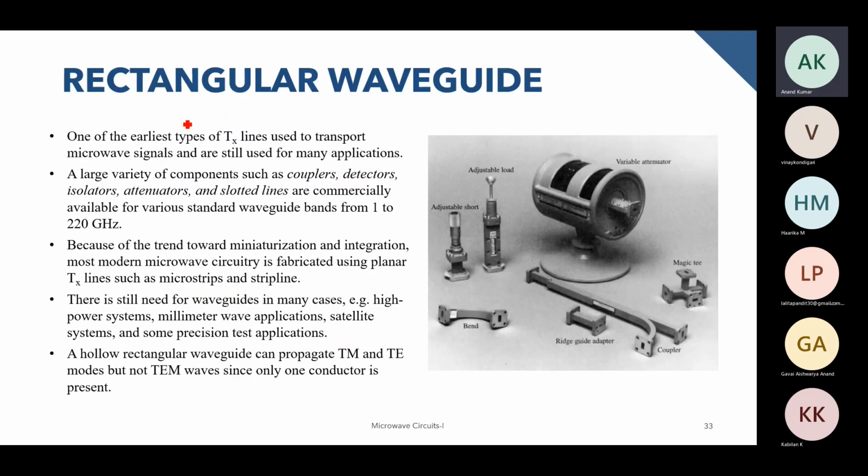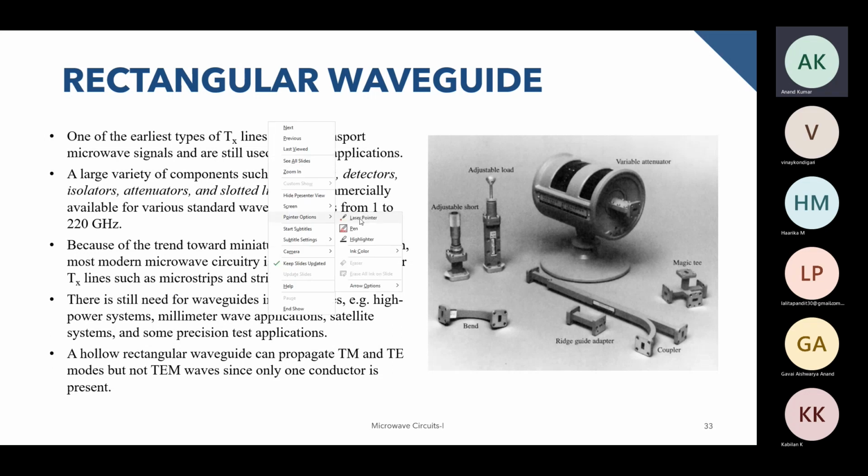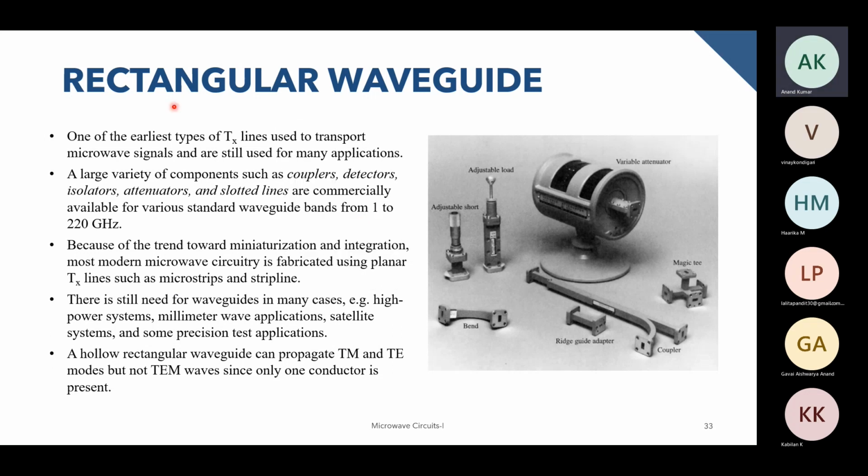Okay, now we'll start with the rectangular waveguides. So let me change to the laser pointer. Up till now, we were looking at parallel plate waveguides, so it has two conductors. Now a rectangular waveguide has only one conductor, and hence it will not support TEM wave propagation.